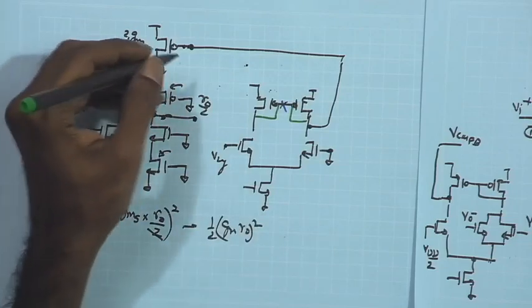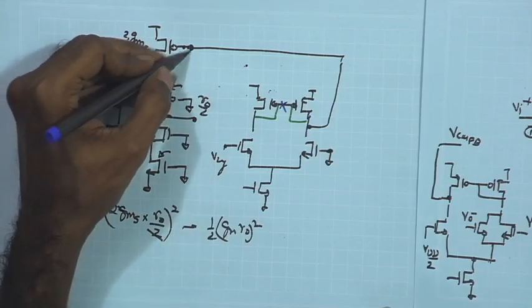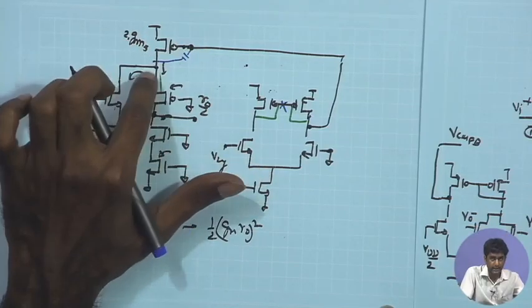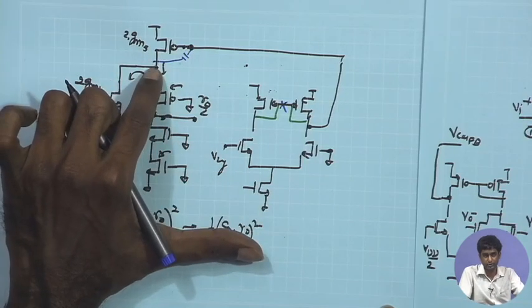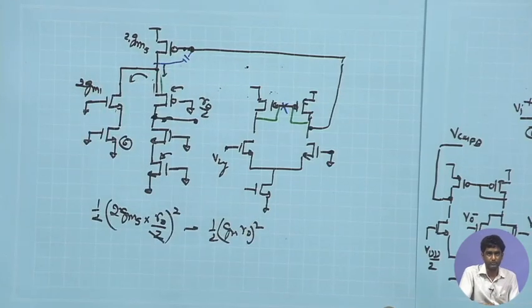For the common mode loop, we can see there is definitely going to be an effective Miller multiplication between the gate and the drain of this particular MOSFET. The gain factor is sufficiently strong, it is gm ro, therefore this can introduce a significant capacitance at this node, right.